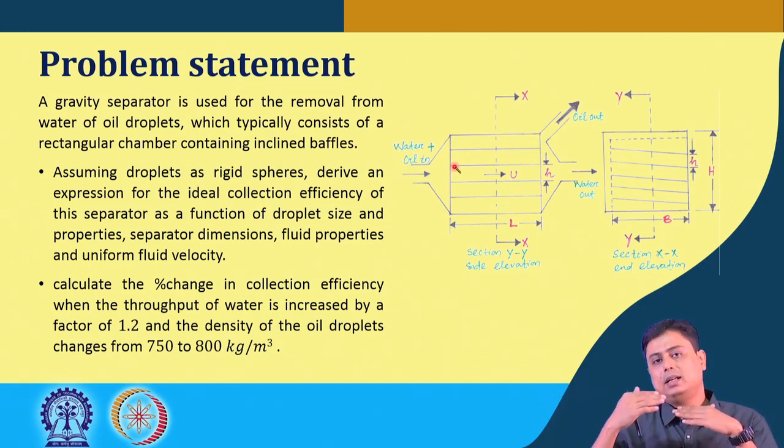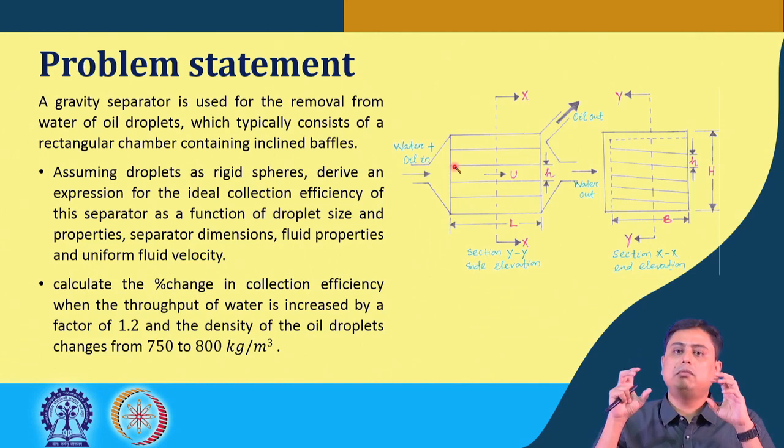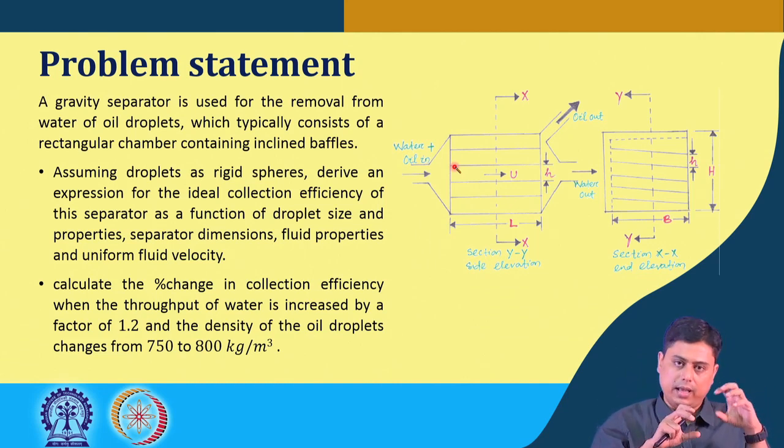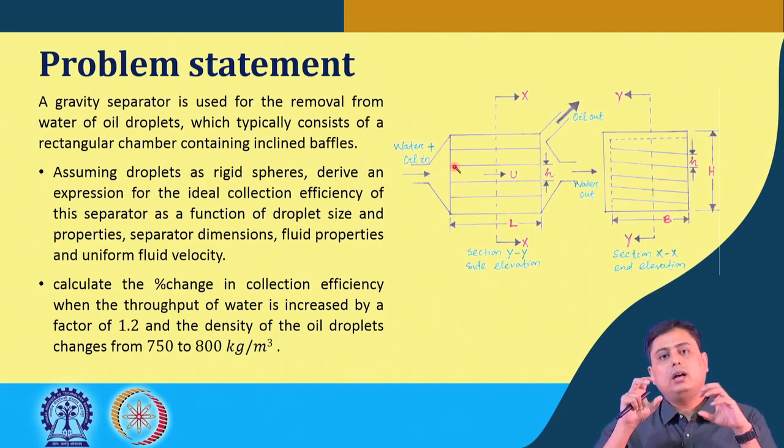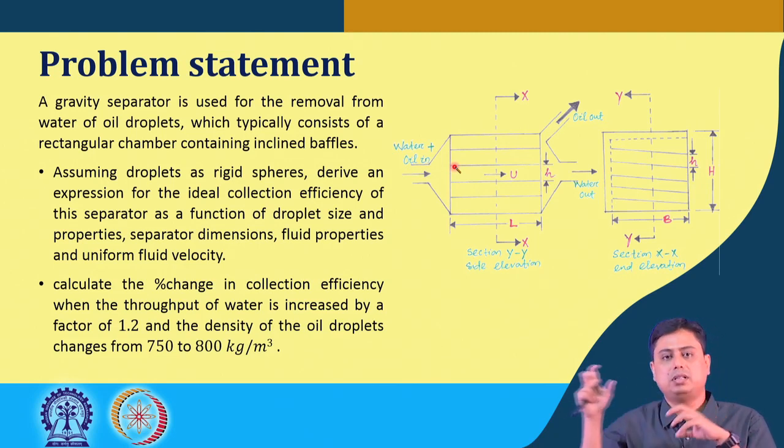The particles that have 25% of this minimum terminal velocity, again this minimum rise velocity depends on the droplet diameter in this case. So, the point is that depending on the percentage of the droplets that have those terminal velocities, exactly the same percentage will be collected.